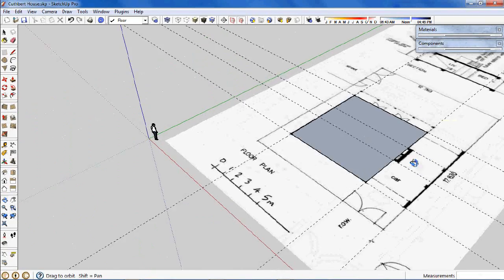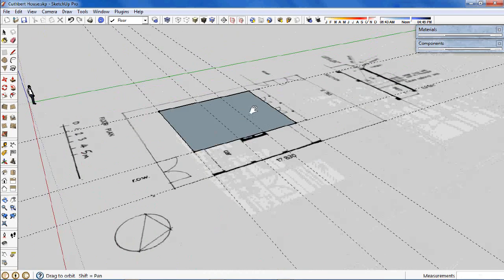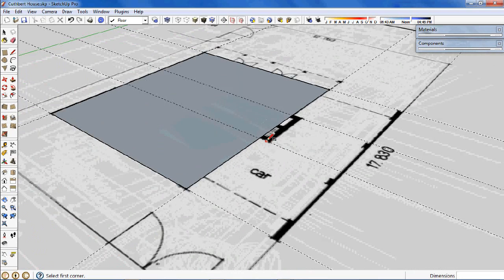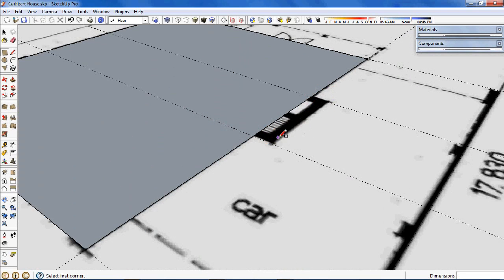And we've just created a SketchUp face, which to all intents and purposes could be the floor face of the building. But there's a little bit else that's happening around the floor face here, so while I'm still in the rectangle tool, I'm going to come to this intersection and out till I'm on line there. Well, I really should have created another construction line to make it a little bit easier, so I might escape out of that command to make that a bit easier.